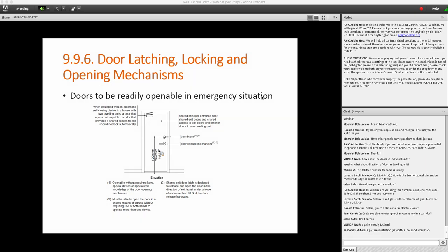Okay. Even though you may be permitted to have electromagnetic locks that release upon the operation of a fire alarm, in that case, you would have to design the release of the electromagnetic lock in conformance with NBC 3.4.6.16(4).